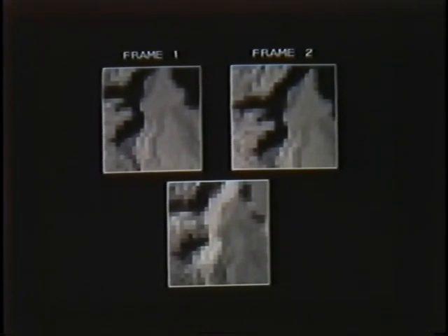Before we begin our jitter estimation process, let's compare the 2 frames just as they are. We'll do this in 2 ways. First, let's difference the 2 frames and note the clutter leakage. Recall that the more 2 frames are similar, the less clutter leakage we should expect in their difference.